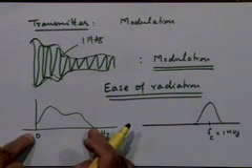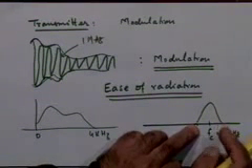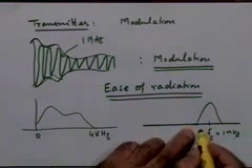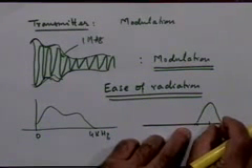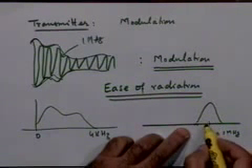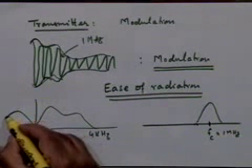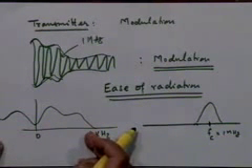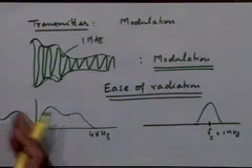Let me go back to this picture that I had some time ago. This bandwidth is 4 kilohertz. This bandwidth at the moment becomes 8 kilohertz. More important than the fact that this 4 kilohertz bandwidth has become 8 kilohertz, because it's 4 kilohertz this way and 4 kilohertz this way. We'll study the nature of this signal later, but if you count both positive and negative frequencies, even this signal has 8 kilohertz bandwidth. Of course, that 4 kilohertz is imaginary, this negative.